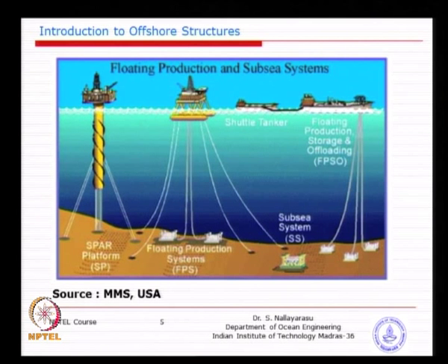So, in the design of a spar, you need to make sure that the center of gravity and center of buoyancy are aligned properly. Always the center of buoyancy should be at the top, so that it becomes upright. And similarly, you have various other hull forms like FPSO systems, conventionally built from simple tankers, but sometimes we have special hulls, something like what you see in this picture, but very rarely. Most of the FPSOs are conversions of existing old tankers, a retrofit.